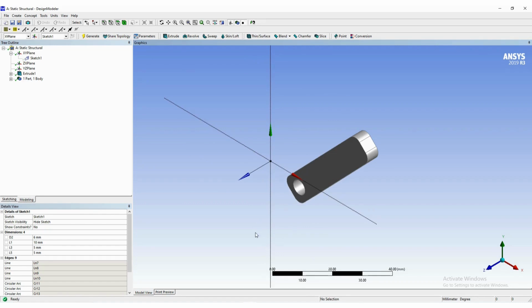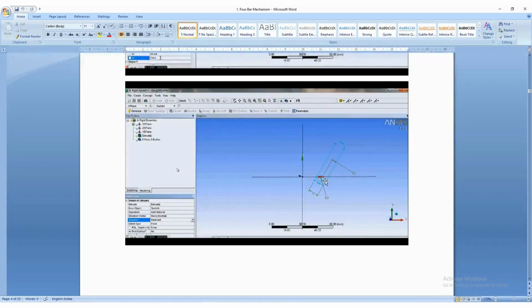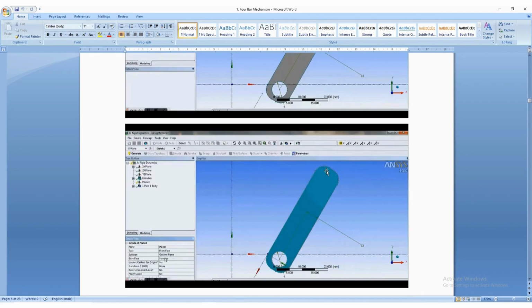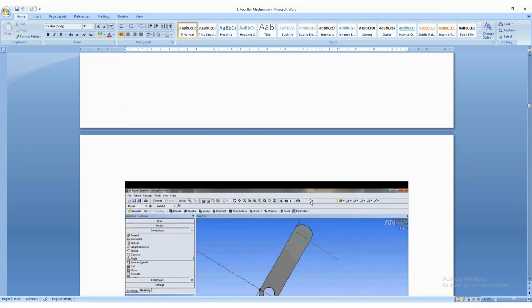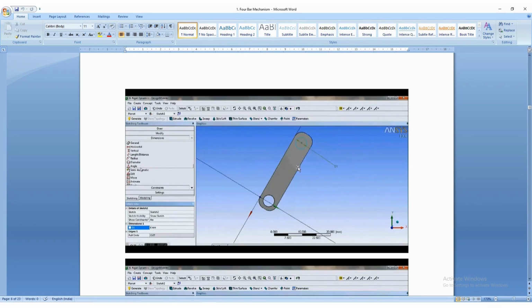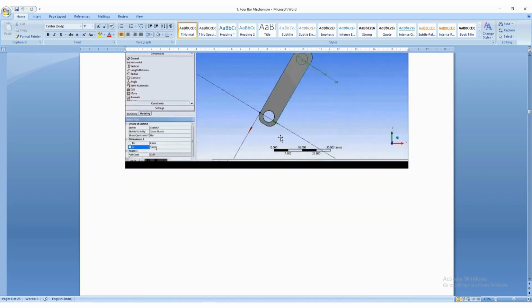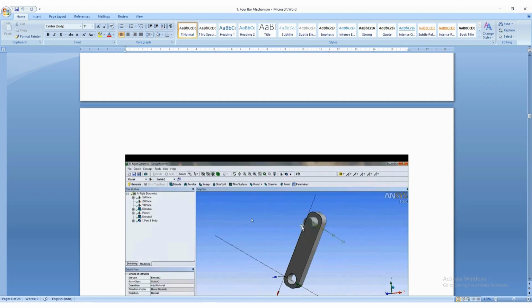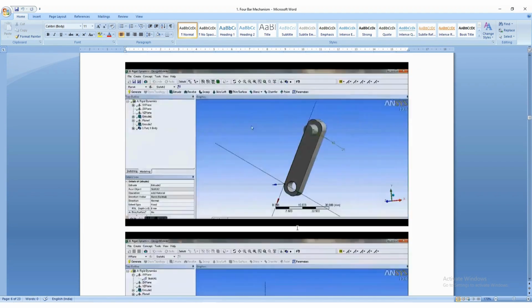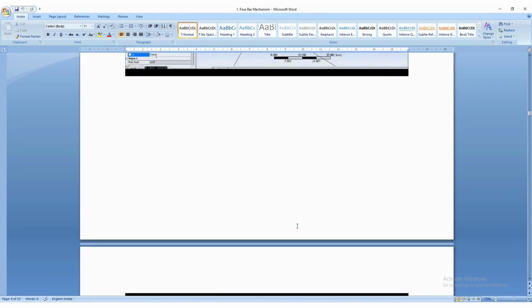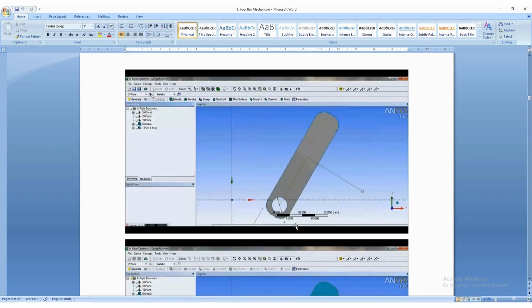Okay, so friends, this we have created for first link, but for that one attachment also we need to create. That we will see how to create that one. For that we have to create sketch onto this front face, and if you see here we can draw the sketch. Okay, and we have to draw this simple circle like this bottom circle, and we have to just add material to that. Okay, and that we have to add on to front side. Okay, so simply we'll go back and see how we have to do that.